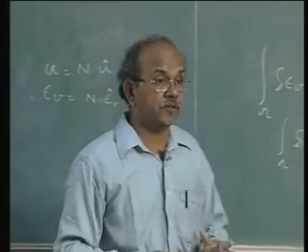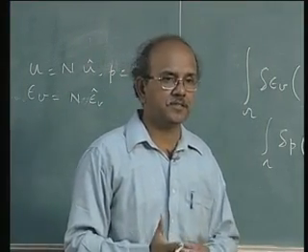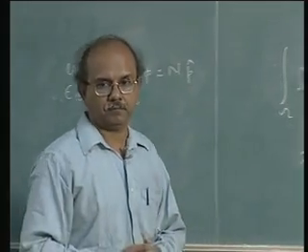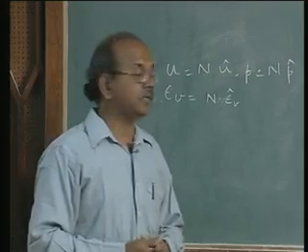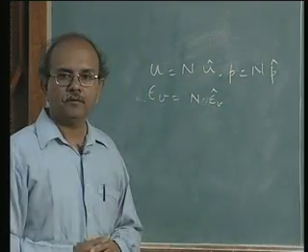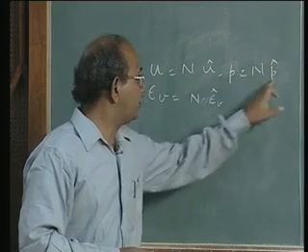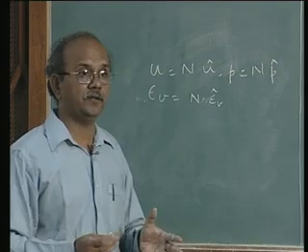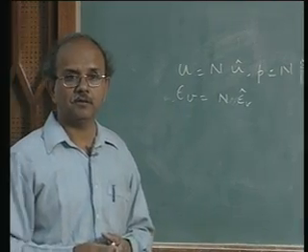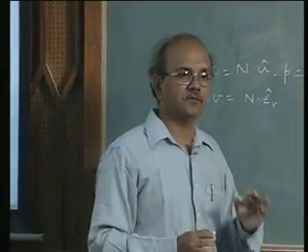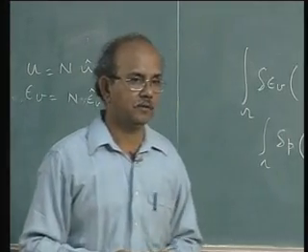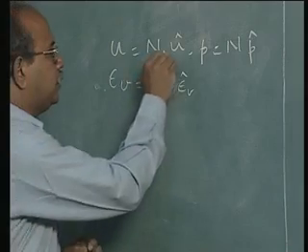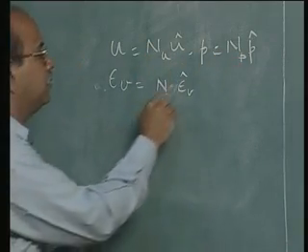The shape functions, of course, as all of you know, depend on how many variables you use. If the shape functions have to be the same, then the number of variables for u, p, and epsilon v have to be the same. But if they are going to be different, then the shape functions have to be different. They are going to be different due to certain very important conditions that we require. So we write them separately as Nu, Np, and Nv.